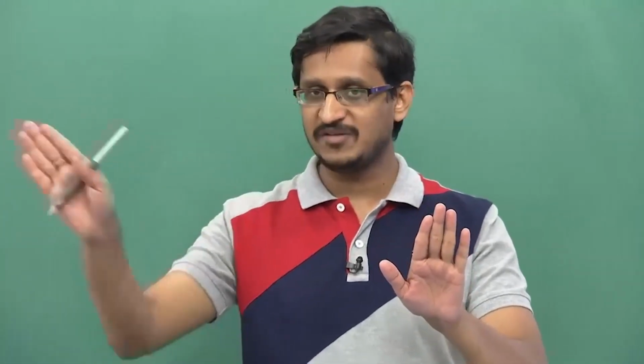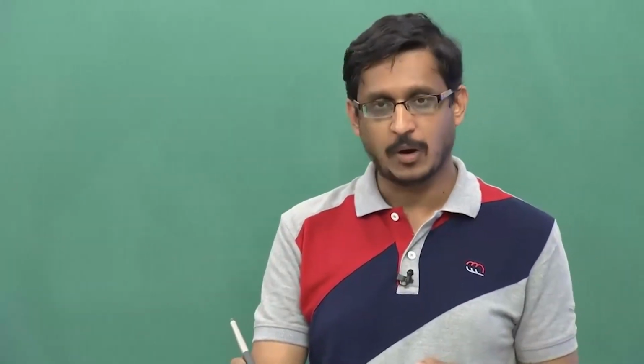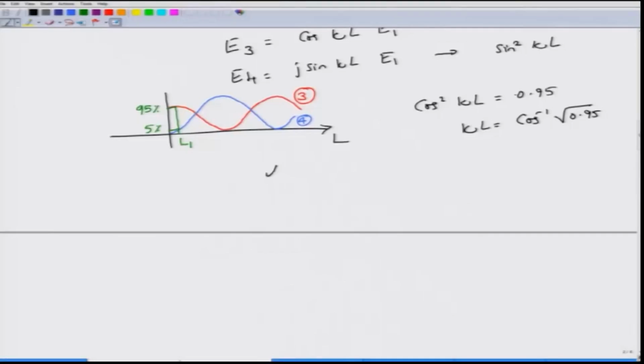Of course, there is no amplification, therefore, alpha must be less than 1. In terms of the power coupling ratio, the scattering matrix is usually written as square root of alpha, j square root of 1 minus alpha; square root of 1 minus alpha, j square root of alpha. Clearly, this matrix also satisfies the relationship. The advantage of writing this one is that you can easily obtain the power ratio, right. So, alpha is the power ratio.